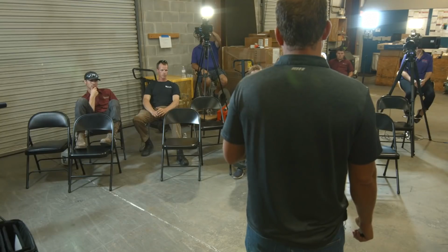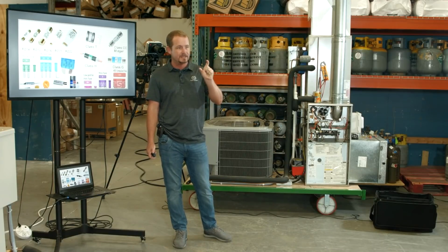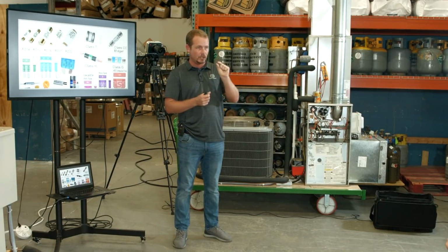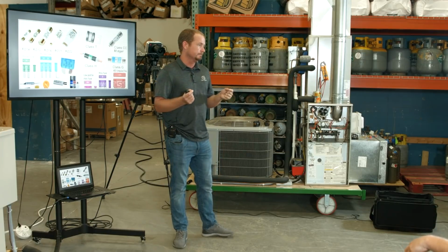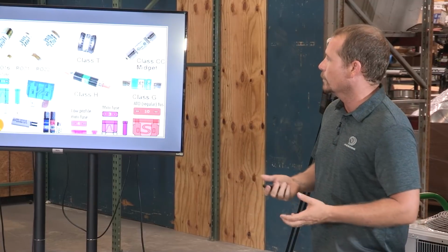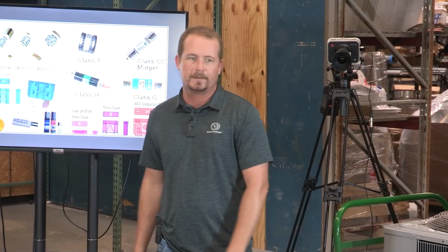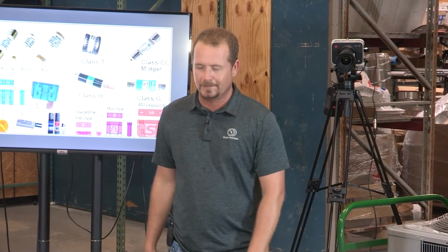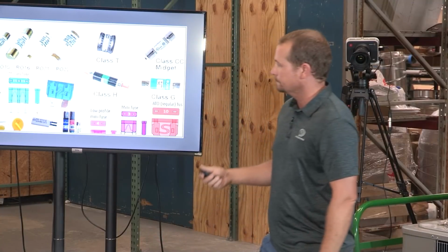Because there's a point at which you may not even have overcurrent, but you have high enough potential that the clearances, the tolerances inside of that fuse could cause an arc. So each fuse has a little different insulation rating and all that. So you wouldn't want to use a fuse that was rated for a maximum of 250 volts on a 480 volt circuit. It doesn't happen very often, but it is something to consider with a fuse.